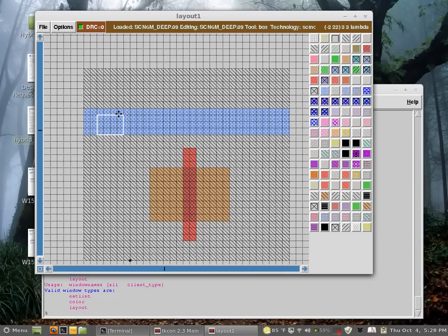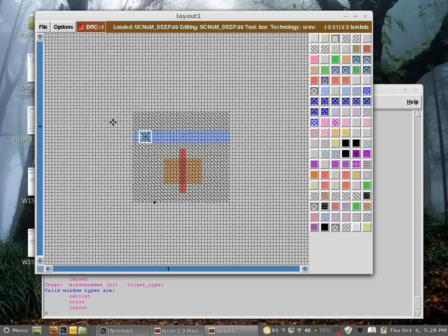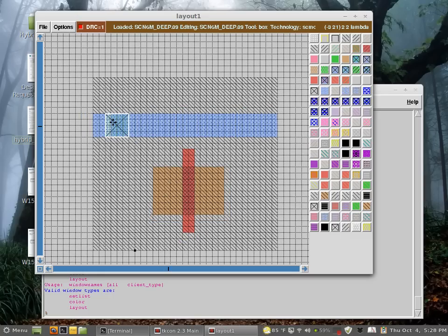By the way, if I want to make my contact 3x3, my body contact, it's an error because the minimum size for the contact is 4x4. I can just do this. How to know these design rules? You can't know them. You memorize them as you work, because you have to correct yourself, and as you correct yourself, you start to memorize.